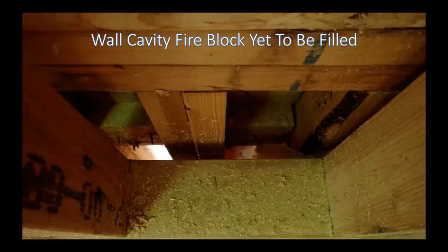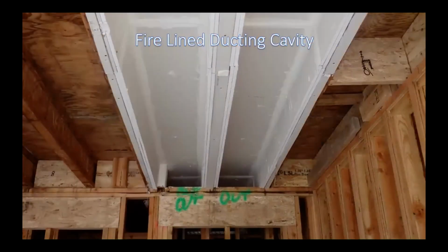So there's obviously a lot of gaps between the party walls that are eventually filled in to have the fire block. In this particular case, I took a photo without that having been filled yet, but that part has to be done. They also utilize a number of ducting cavities where they actually fire line them as well. For whatever purposes, maybe these areas have got some sort of downlights and other things like that. I don't know, but at the very least maybe the ventilation vents come down through those areas, and so they provide some protection around those areas as well. That's a very good idea too.